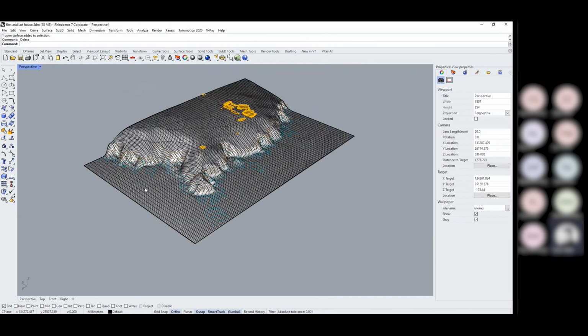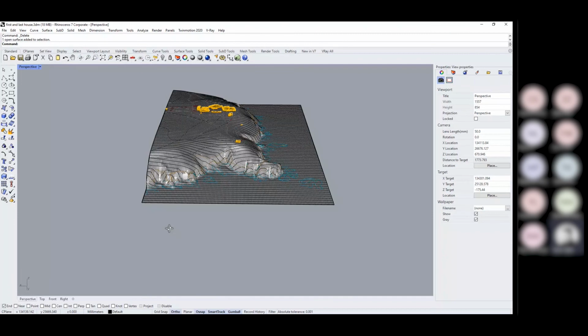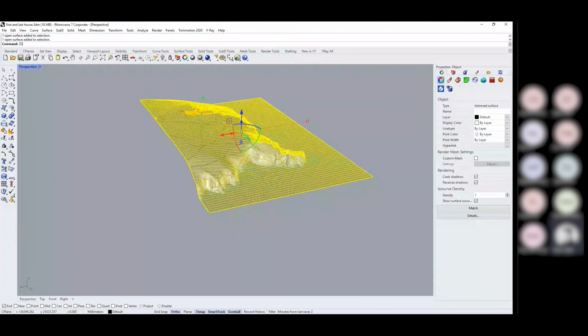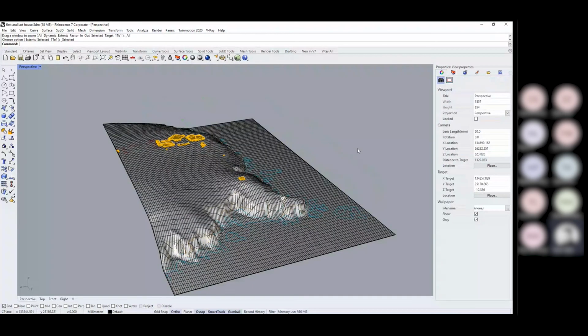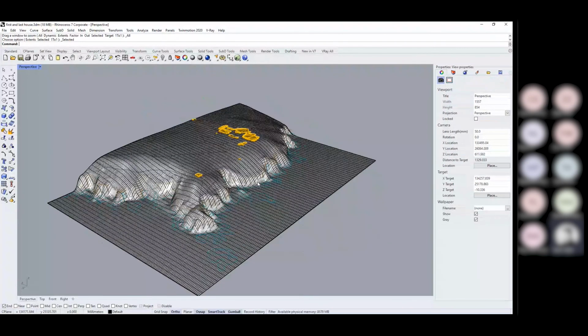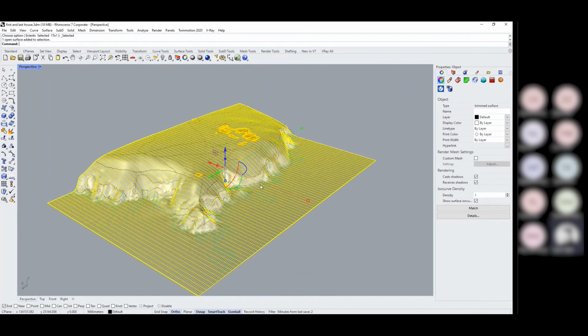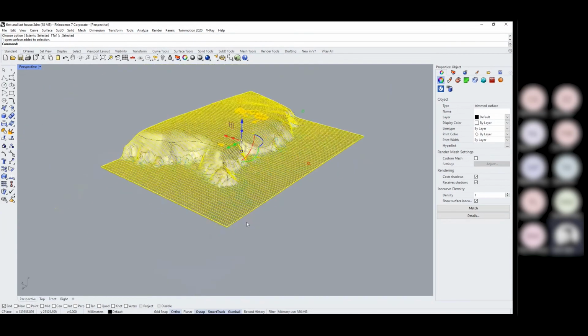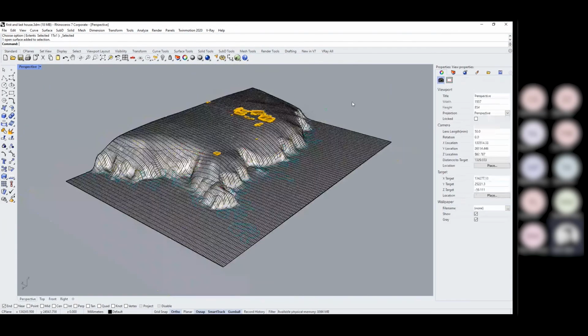But at the minute, let's say I wanted to CNC machine this model. Some CNC machines will let you just export surfaces, typically as either STL, OBJ, or 3DS format, but some of them will want them to be closed watertight objects. And I would always recommend you make it as a watertight object. For those of you that don't know what I mean when I say watertight object, I mean something that's solid.